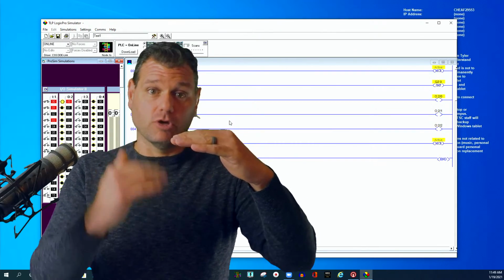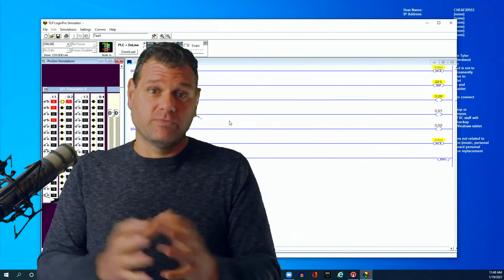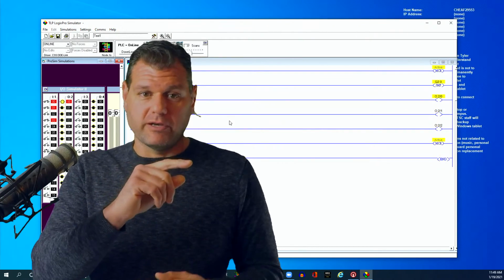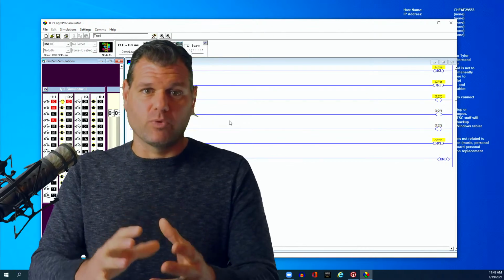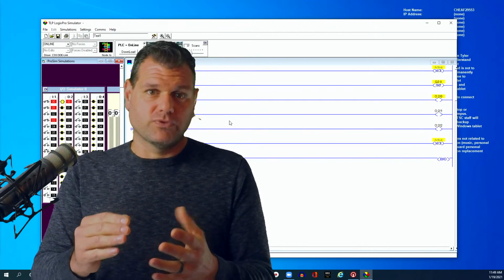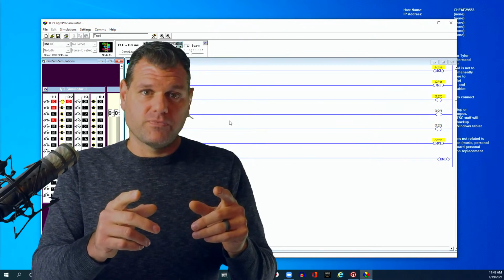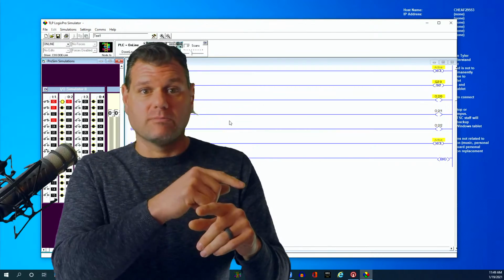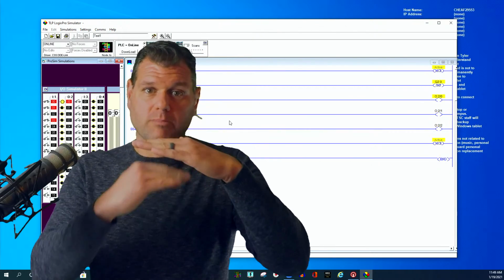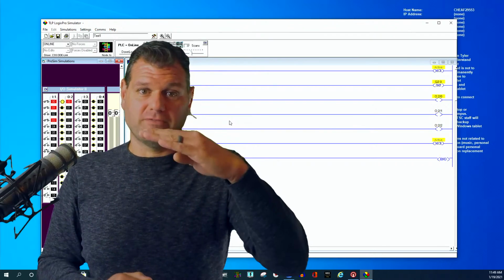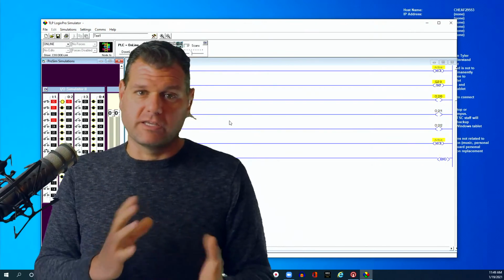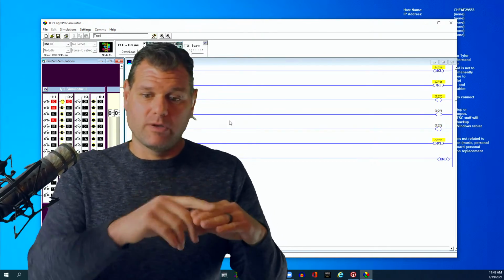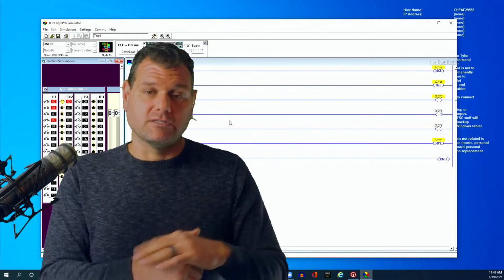When the temperature is below the set point, it says, I need more heat. So at that point, you could jump to a subroutine, and the subroutine does nothing but light the burners and get everything set up the way it's supposed to be, just so you can get that heated back up. Once it's done with the subroutine, once it gets to the very end, it jumps back to the main routine, and it comes back in one rung below where you left. So if you left on rung 50, it'll come back on 51. So just kind of keep that in mind too. It doesn't skip over things in the main program. It stops scanning the main program, it scans the subroutine, and then it comes back into it.